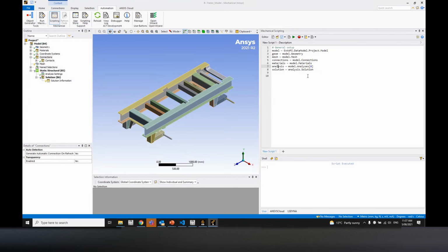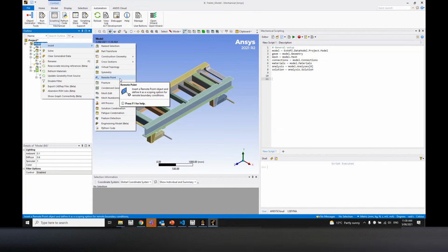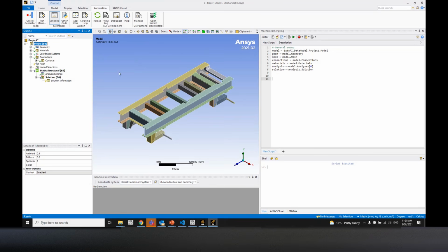Okay. And the former option of recording your setup seems more practical. Yeah. Okay, so I'll start recording a few things. Maybe I'll start recording the point mass. I think that's a good example. And then I'll go through how I've got the point mass set up in my code fully as well. The point mass would be under model. So let's add a point mass first. To get a point mass, you need a remote point, so let's add a remote point first.